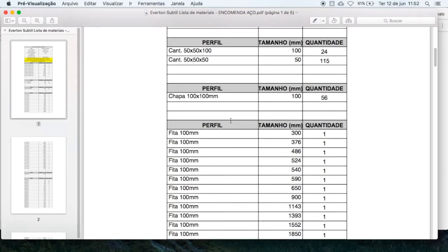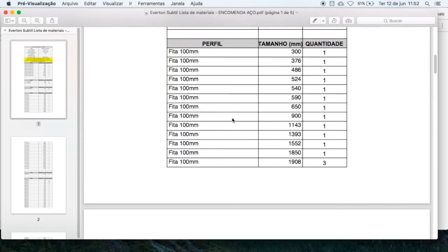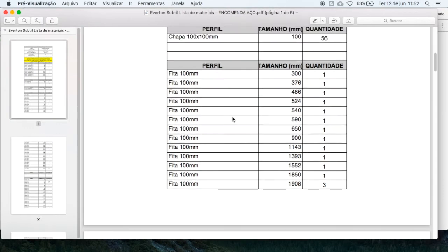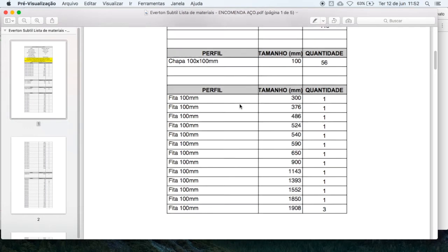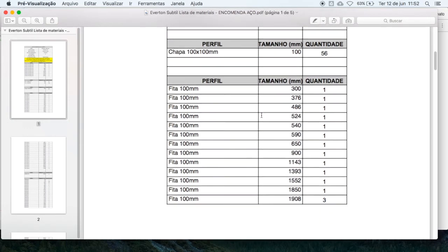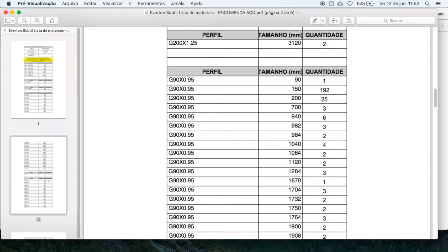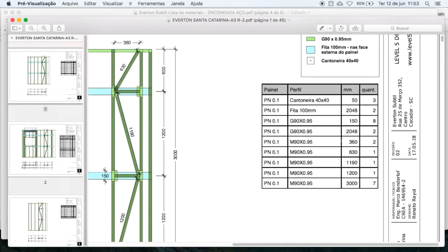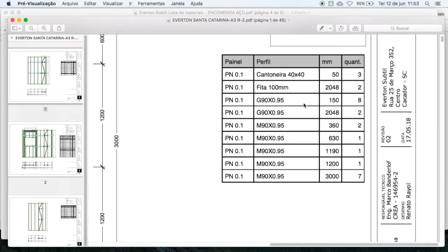A very clear example is the light gauge steel frame profiles. With the quantity information in the report, it's possible to make the budget of the building. But for the purchase of the material, the ideal is to have the table with dimensions of each profile, so that we can order the material cut to measure. Like this one, other materials may also require additional information or drawings to get the necessary quantification of materials. All of these details should be discussed with the contractor when it comes to hiring a 5D BIM service.